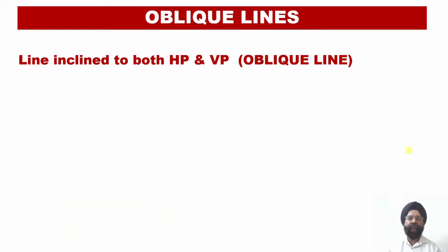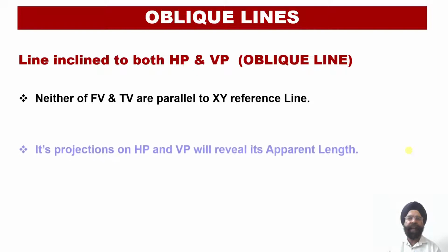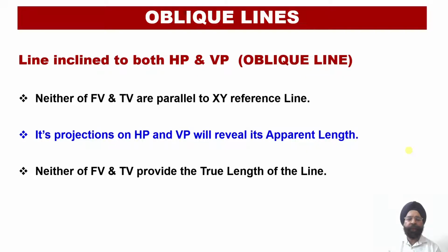An oblique line is one which is inclined to both the reference planes, that is the horizontal plane and the vertical plane. Due to this inclination, neither the front view nor the top view will be drawn parallel to the XY reference line, and we obtain only apparent length projections of the line onto the horizontal plane and the vertical plane. Neither view provides the true length.